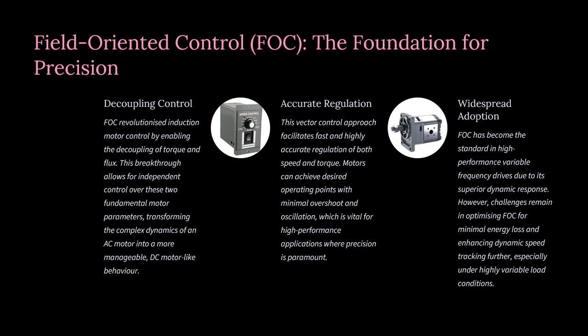The vector control approach facilitates fast and highly accurate regulation of both speed and torque. The motor can achieve desired operating points with minimal overshoot and oscillations, which is vital for high performance applications where precision is paramount. It has led to the adoption of standard and high performance variable frequency drives due to the superior dynamic response.